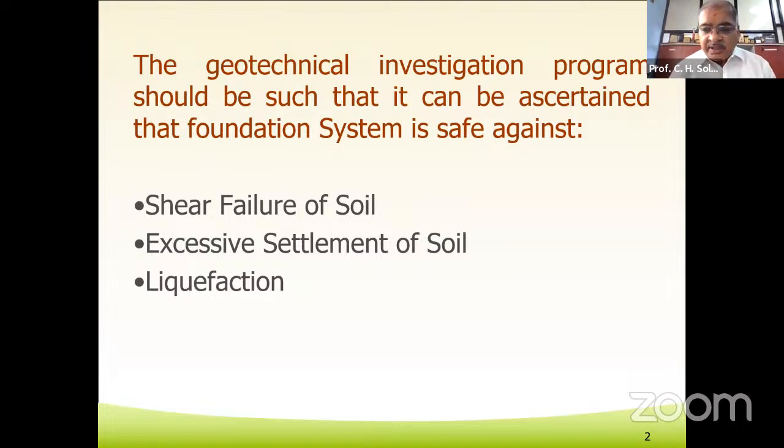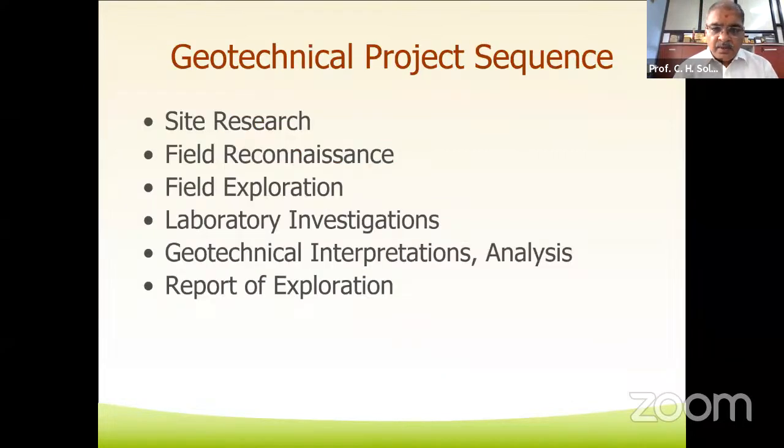We are supposed to know the susceptibility of liquefaction based on the strata at the foundation depth as well as below the foundation. The geotechnical project sequence consists of the site research, field reconnaissance, field exploration, laboratory investigations, geotechnical interpretations and analysis, and report of explorations.